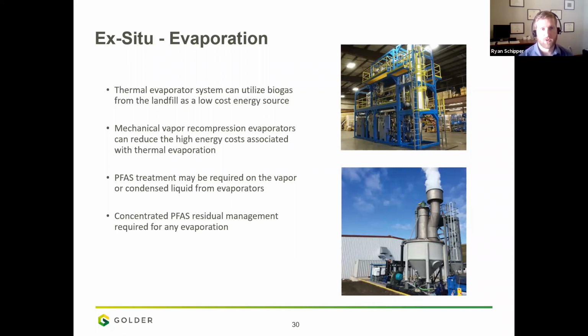We're taking that steam and recondensing it to create a relatively clean water stream, although there may be some precursors and PFAS in it that would then require treatment, but we have stripped out a lot of the complexity of the water. Mechanical vapor recompression evaporators are much less energy intensive because they recover the heat from the steam to drive the process.